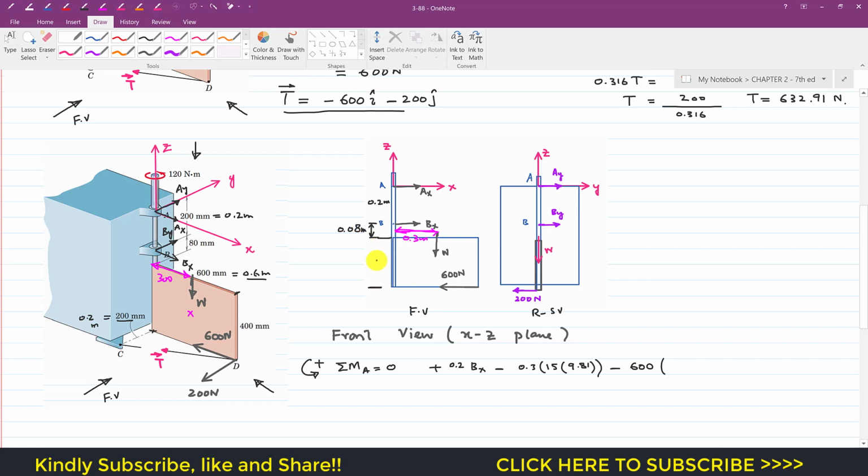And similarly, this height of the plate is 400 mm, or we can say that this is 0.4 meters. So now the perpendicular distance of this 600 Newton force from that point A is this total distance. This is 0.4 plus 0.08 plus 0.2. So 0.4 plus 0.2 is 0.6, so this is 0.68. Or we can say that the distance of this 600 Newton from that point A is this 400 plus 200 plus 80. So this is 680, and 680 divided by 1000 will give us 0.68 meters.